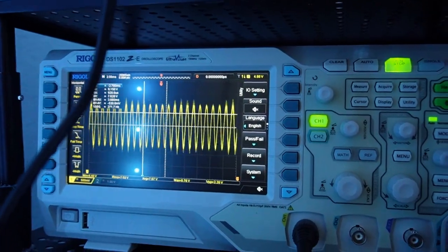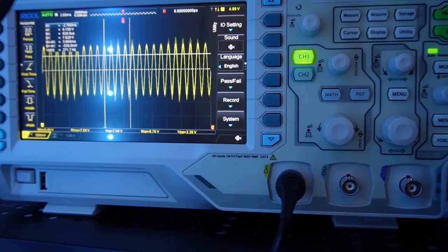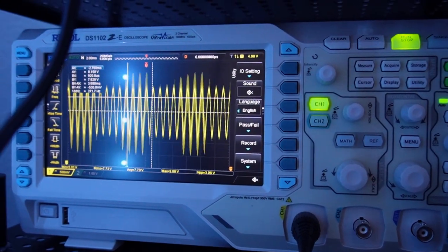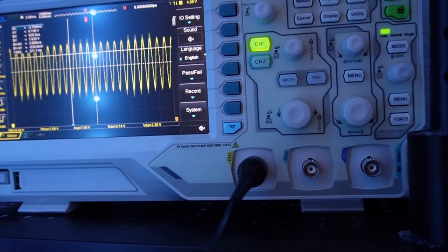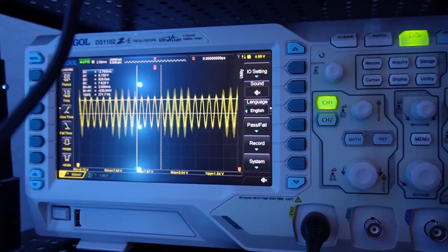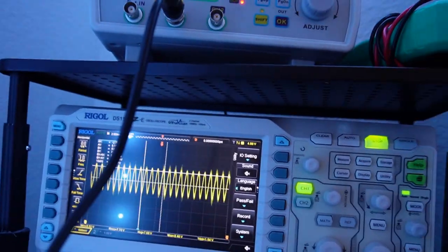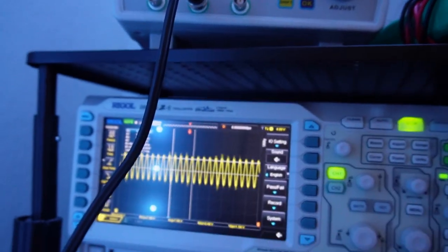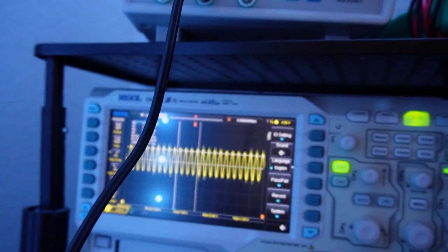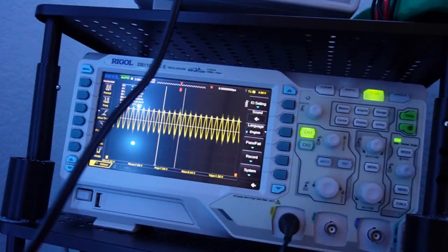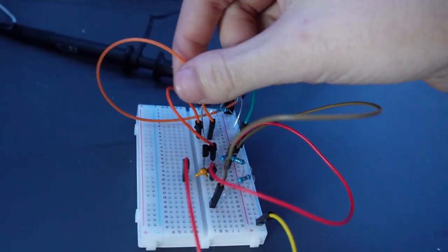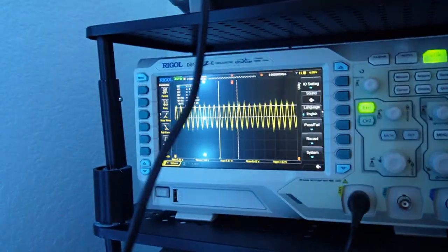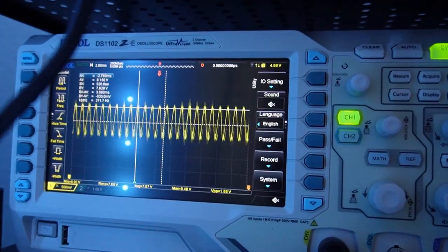in fact, I will leave this on the oscilloscope. Once I connect it, we see a voltage drop here. And that's now because it's splitting this voltage with the other load. So now, instead of having the oscilloscope probe the collector terminal, I'm going to have it probe the load. And we're seeing around 1.6 here.